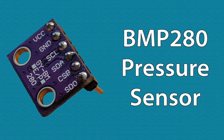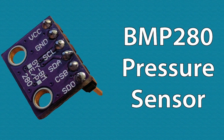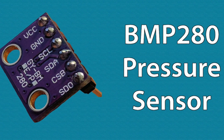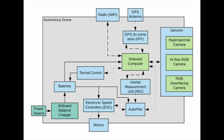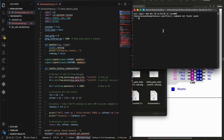It's a very simple sensor, very cheap, lightweight, and like I said, it works with a serial bus, so very simple technology. And it's a good choice, but for embedded systems like a drone, which are complex and they integrate different systems, different hardware, it's not robust enough. And so we need some other protocol like CAN bus to wire the communications between all the systems.